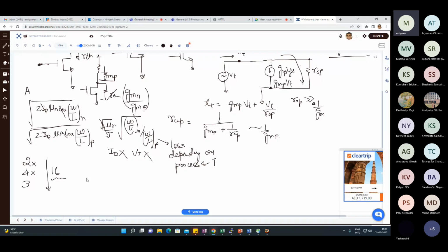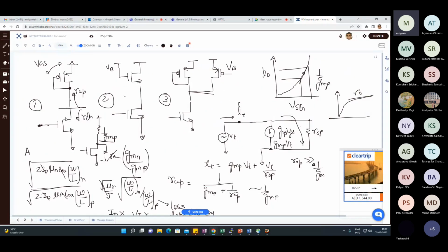Still, as compared to a common source amplifier with active load, this gain is lower. There you are talking about a gain of a few tens at max. So generally it may be good if you limit yourself to a gain of say 2, 4, 16, or that order. Of course, the Miller effect will be there, but because the overall gain targeted in this design is smaller, the Miller effect will also be relatively smaller.